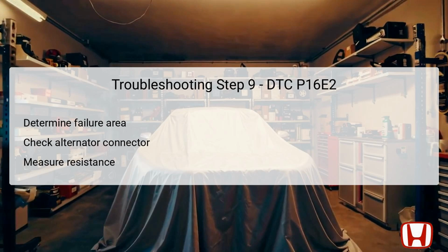Next, measure resistance between the test points using the disconnected connectors. The measurement will occur at the same test points as previous steps: the female terminal 1 of the alternator connector and body ground. Results of 1 megaohm or more will guide you to the next step, whereas lower values will indicate additional issues needing rectification.